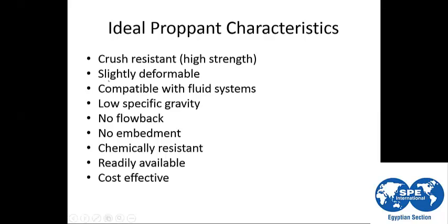Also, it should not deform after applying stress on it, because if the shape of the proppant changes from spherical shape to other shapes, this deformation will reduce its permeability. Also, it should be compatible with the fluid system. It should be inert and not react with either the formation fluid or the frac fluid.